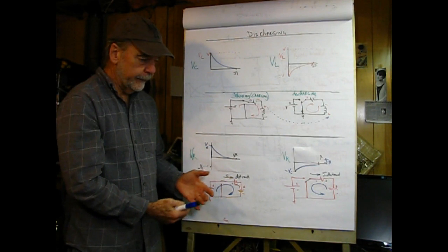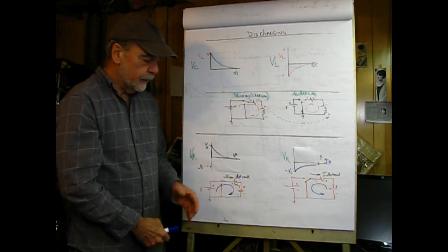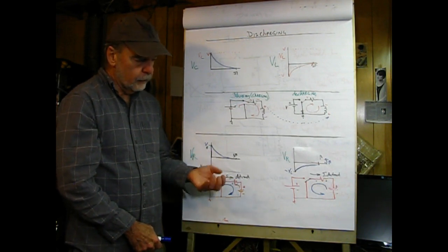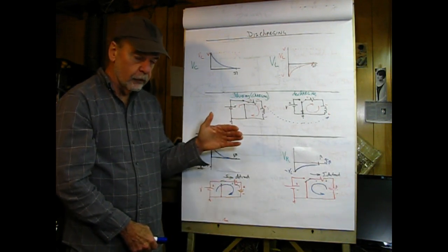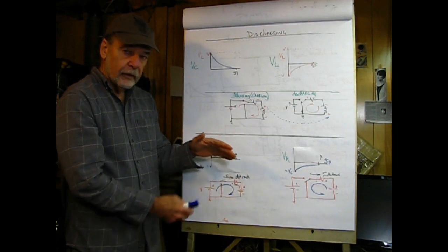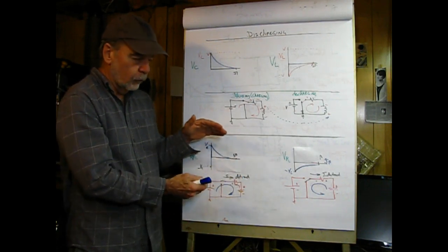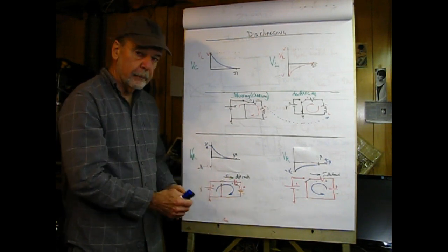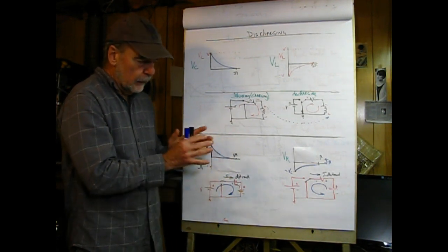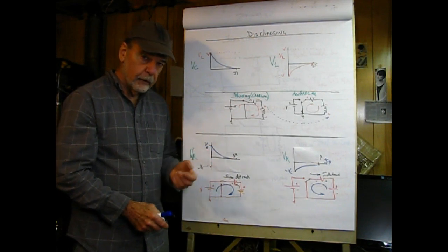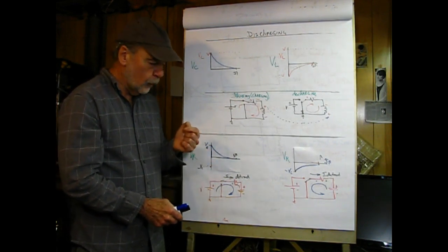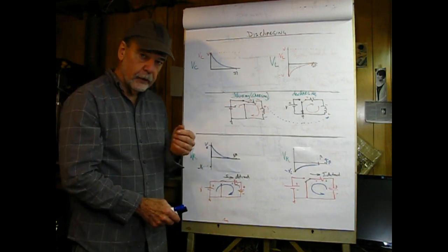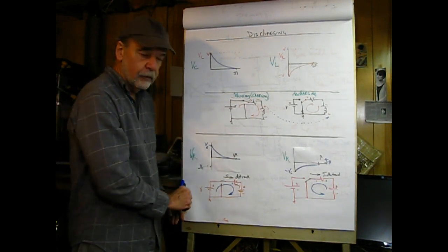Now, how do you find out what's what? First you have to know how the part operates. The capacitor starts out at 0 voltage and charges up to the source. An inductor starts out at 0 current and all of the voltage is across it, and then the voltage will decay across the inductor as time passes. When you get the fundamental operation of the capacitor and inductor down, and you know how to use KVL and the two charging and discharging exponential equations, you can figure out anything.